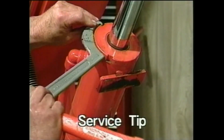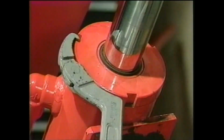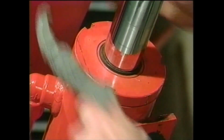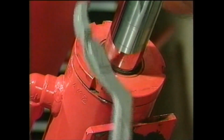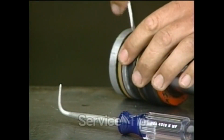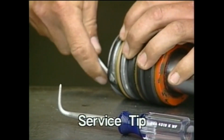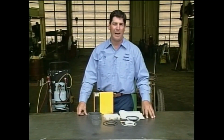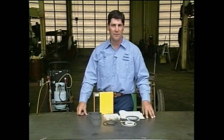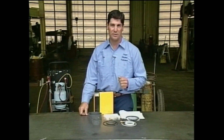Before removing a cylinder from the machine, check to see if the retainer is threaded. If so, loosen the retainer by letting the machine stop the cylinder from turning. To prevent scratching the piston's metal sealing surface, be sure to round the corners of any service tool you use when removing or installing seals. There are many types of seals, packings, and wipers used on cylinders. Be sure to check with each manufacturer for replacement parts and correct installation procedures.